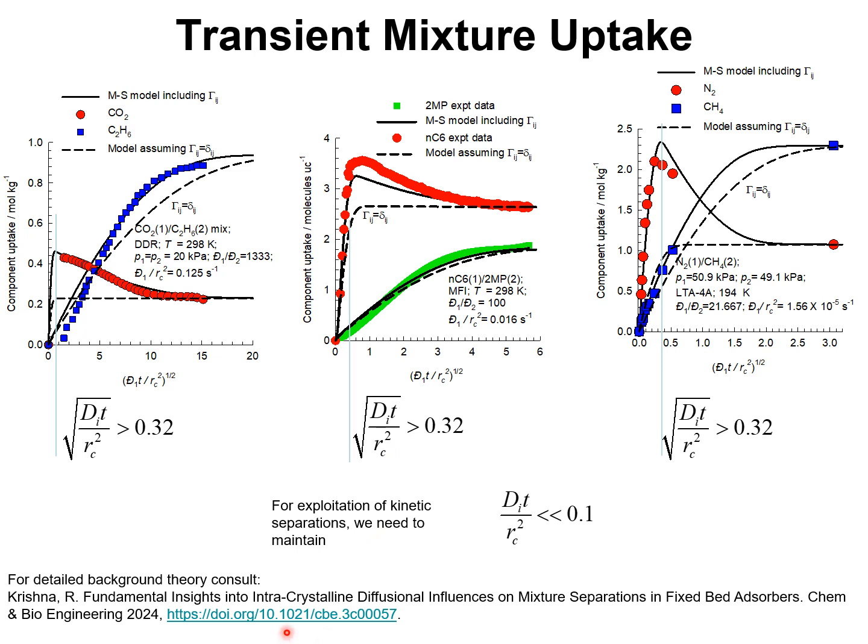In this paper that is not yet online, I argue that for kinetic separations to be effective, we need to operate at conditions wherein the diffusional time constants multiplied by the contact time in the fixed bed adsorber is smaller than 0.1.